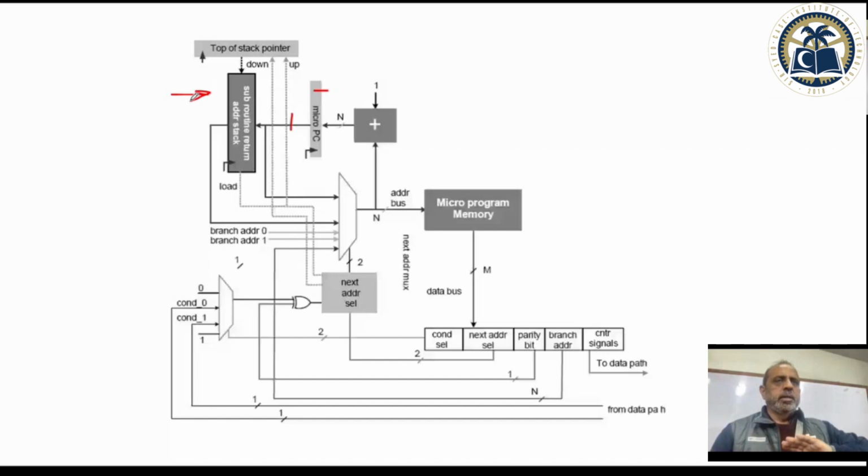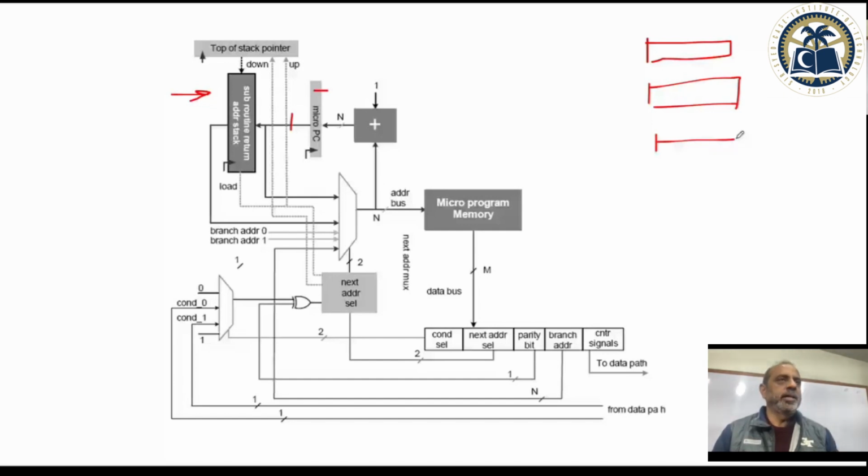So the address of the next instruction goes there. Then you call another subroutine, and again that address will go into that LIFO. If you want to support this 4 times, remember we did this LIFO and FIFO. They're so important that if the stack is full or empty, and you say return where there is nothing because you have never jumped, or you call subroutine four times and you are pushing the 5th value, it must generate an error, so that the user knows you have already called 4 subroutines and it does not support a 5th subroutine call.